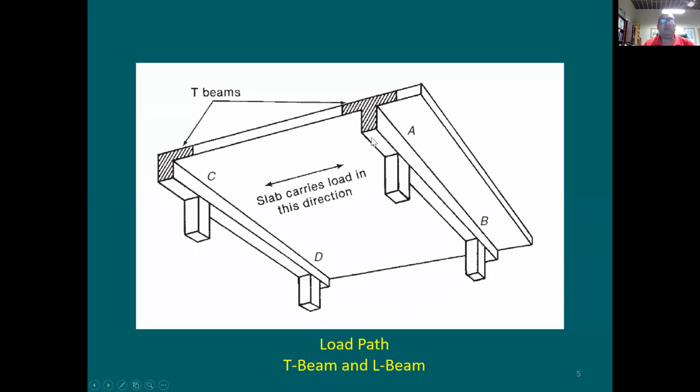Now looking at the beam, where is the beam section? Someone's gonna say the beam section is gonna be from here to there, the rectangular section. Someone else is gonna say, how about the slab itself? Why didn't you consider a section of the slab itself to be working with the beam and form the beam with you? Because someone else can say, is the beam gonna be from here to here only? It's gonna be the depth of the beam. You guys remember the depth of the beam that we discussed? The edge, that we call total depth of the beam. Now, where's the total depth of the beam? Is it from this point to this point? There's gonna be the total from here, bottom of the beam, all the way to the top of the slab.